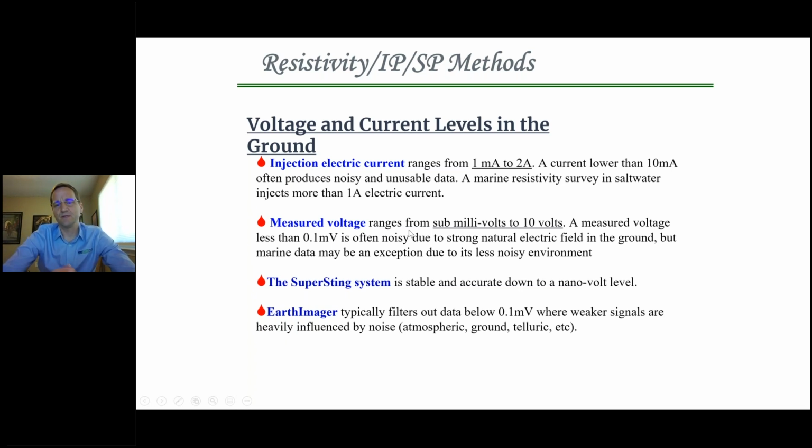So that's why the instrument has to have an isolated battery, nothing else connected to it, or a nice generator like I showed earlier, and quality control of your cables. Keeping the insulation good on those will prevent noise. That's a relatively low-cost item to replace periodically.